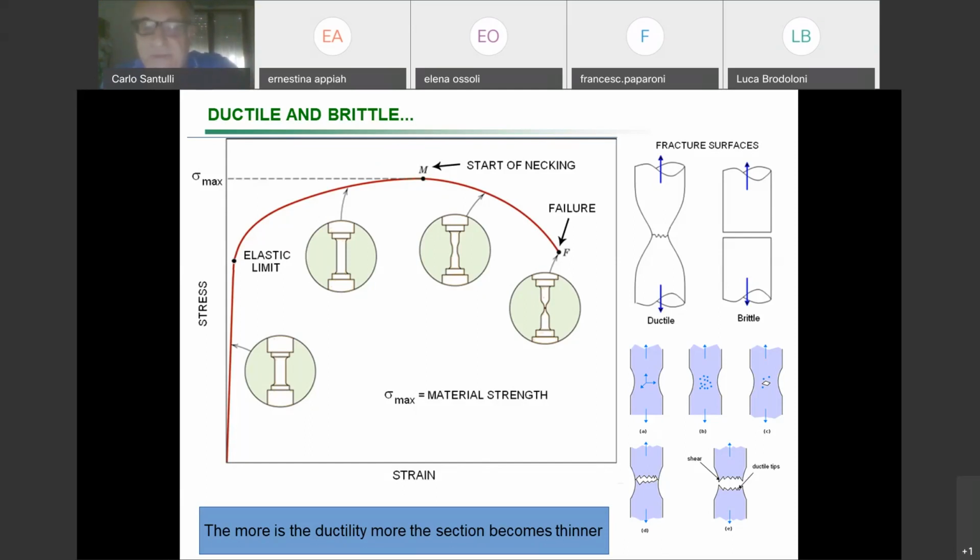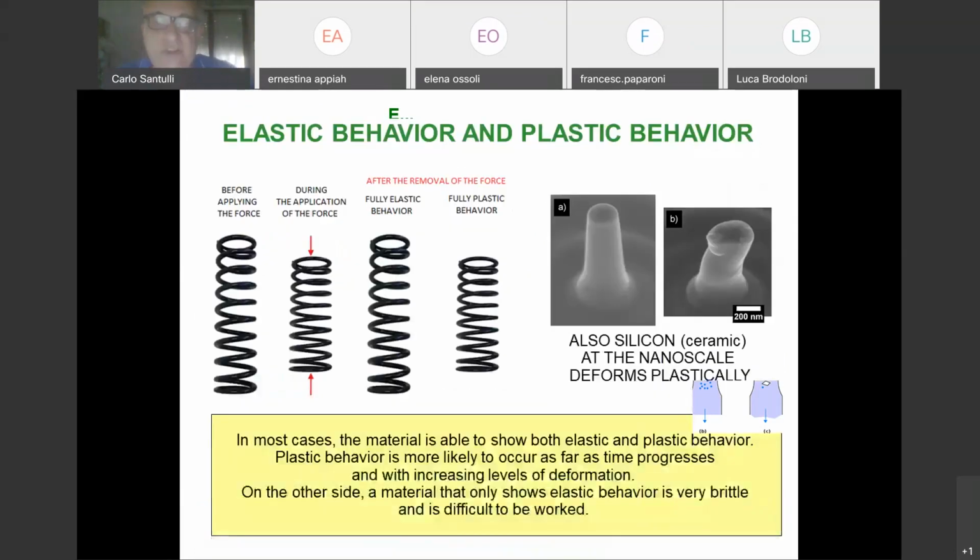It is important because you need to know which kind of load you are able to apply to your material. And sometimes it's not even sufficient, because with fatigue, if you want to apply that a million times, say if you have a bolt which is in a wheel in a car, and the wheel over the life of the car can turn millions of times, you may need to stop well before that in order not to have fatigue effects. So we need to have a kind of over-dimension of our materials, of our structure.